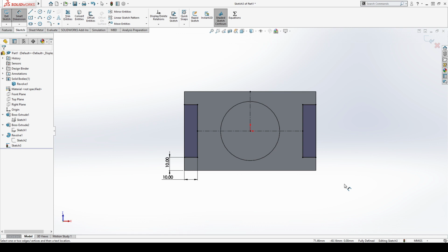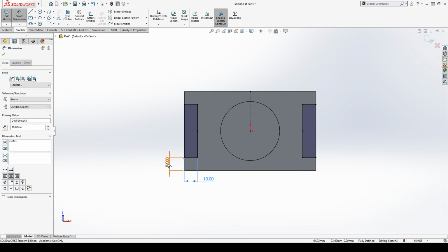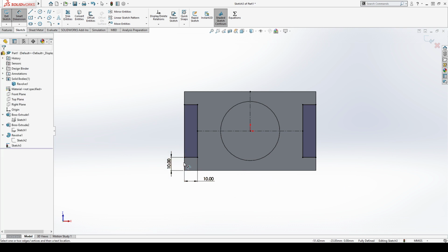It's a little bit of review of what we were talking about last week, where we want to add in as many of those relations as possible first to make as few dimensions as possible in our sketch, so the dimensions are actually defining what we want and not just arbitrarily making our sketch look nice. So it's making this cutaway 10 millimeters deep, and then I want this foot to be left over to have a 10 millimeter value there. Cool.